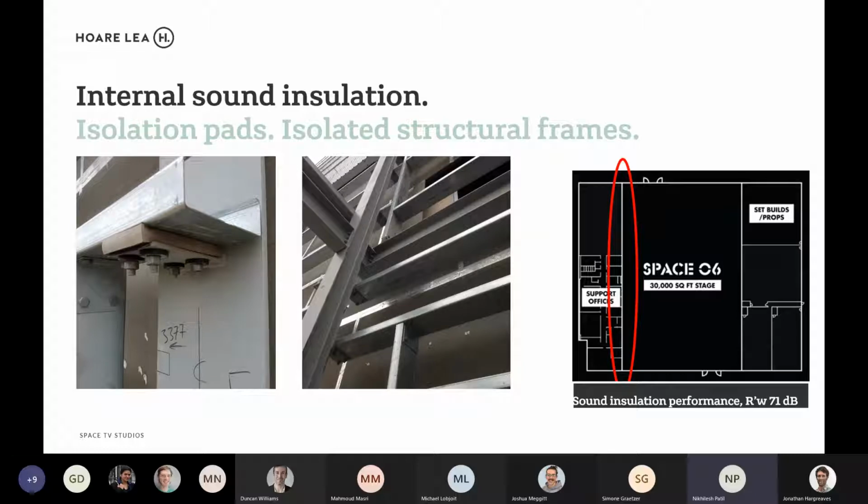And when I say a soft joint, it is something where we can have a break between the structures through means of isolation, some resilient isolation or foam, such that there's no direct transfer of energy or flanking energy into the isolated structure. So on the left, as you can see, at the few connections that could not be avoided, we engineered a specific soft acoustic joint with the help of specialist supplier inputs. And these are the little details that need to be taken care of for every project to make sure your acoustics doesn't get compromised.